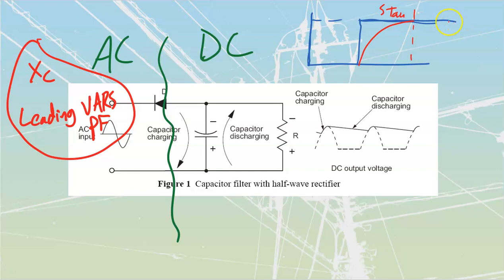And then as long as the voltage is up there, it's going to maintain it up there. It's opposing the change in voltage. See how the voltage went from 0 to full? This thing opposed that. It slowed down that rate of rise. Same as when my voltage is going to drop over here, my cap at that point is going to oppose that change.